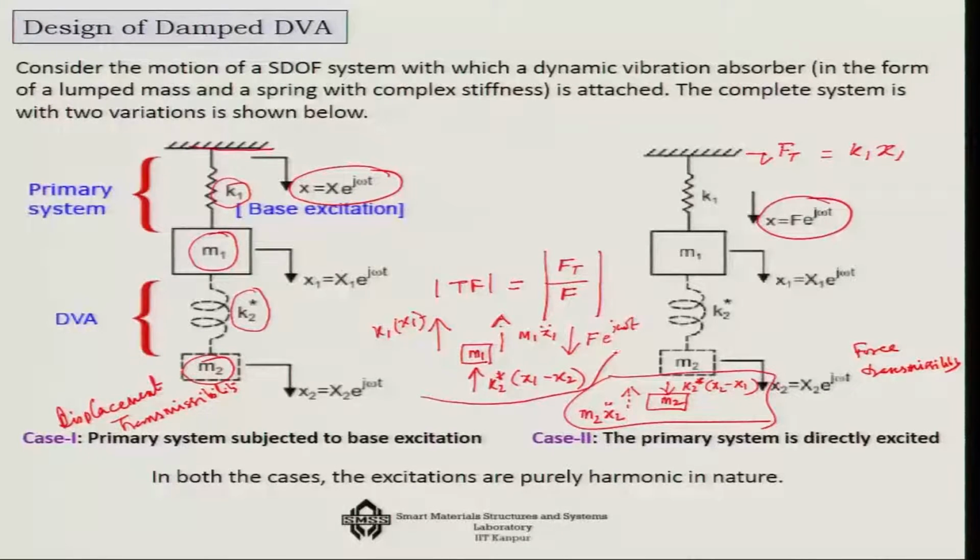So, you can get a governing equation corresponding to this free body diagram. I leave it as an exercise for you, and you can get one corresponding to this, and then you should be able to find out the transfer function for the force transmissibility, and you can confirm yourself that this will be equal to the displacement transmissibility of the system.